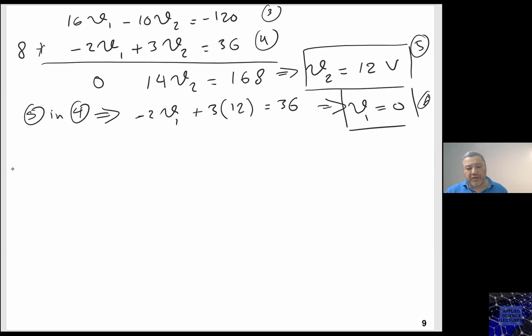So again, the nodal analysis is KCL based, and if you notice, when we wrote the nodal equation by inspection, and we were standing on V1, we were going V1 minus V2 divided by R. This is a current. In other words, we're looking at the summation of the currents, but this is done in a very nice and simple way that we call by inspection.